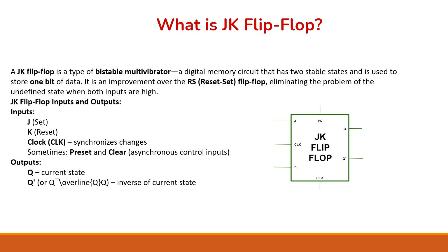JK flip-flop inputs and outputs. Inputs: J (set), K (reset), and clock CLK for synchronized changes. Sometimes preset and clear. Outputs: Q, the current state, and Q prime, the inverse of the current state.